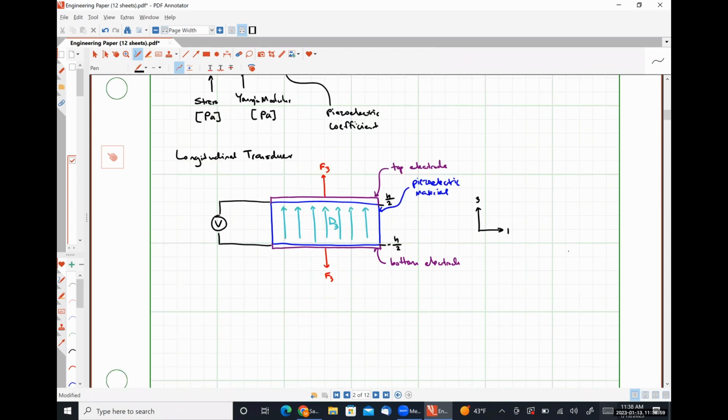So in this particular configuration, the electric displacement in the 3 direction is given by epsilon, the permittivity of the piezoelectric material, multiplied by E3, plus e33, our piezoelectric coefficient, times S3, our applied strain, or epsilon E3 plus e33 times the derivative of u3 with respect to capital X3. And I'm going to unpack what that thing means there.